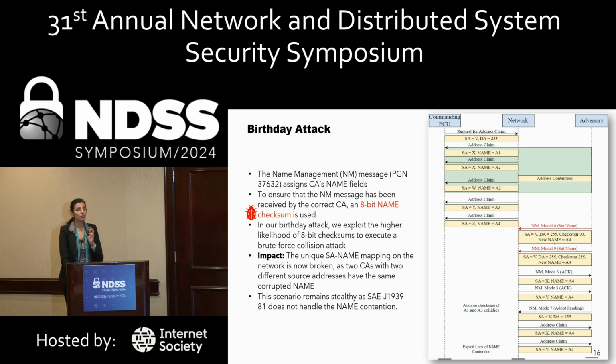Exploiting the fact that checksums are inadequate for security purposes and prone to collisions, we fabricated this brute force birthday collision attack where we impersonated a commanding ECU and brute forced the entire checksum range 0 to 255, assigning new names to the controller applications on the network.